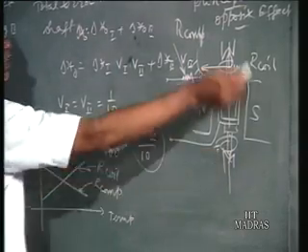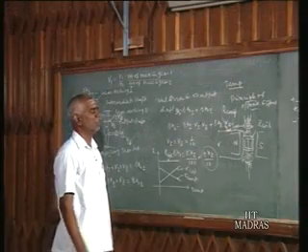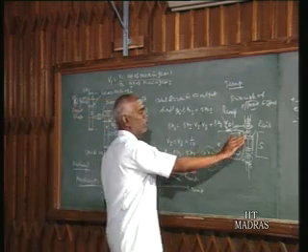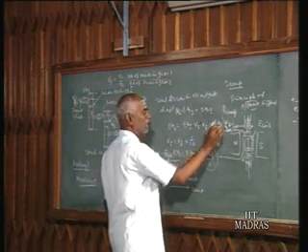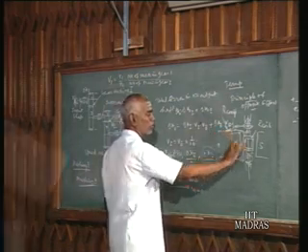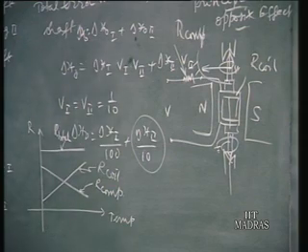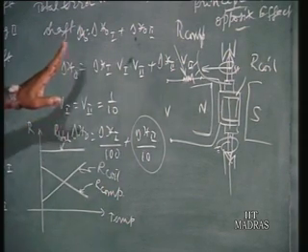Now irrespective of the temperature of functioning, where the instrument is made use of, the temperature atmosphere, you will get the correct reading irrespective of the temperature. For a given voltage, the R total remains constant, so the current will always be the same for a given voltage irrespective of temperature. This is the principle of opposite effect. That is temperature.